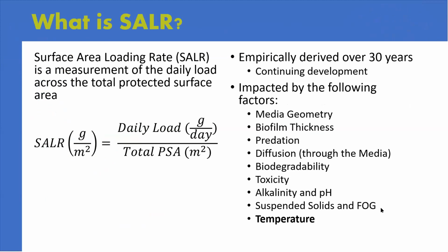So what is your surface area loading rate? Surface area loading rate is a measurement of the daily load, your daily BOD load, across the total protected surface area of your media. Really, it's meant to be a measurement of how much load my system can handle.